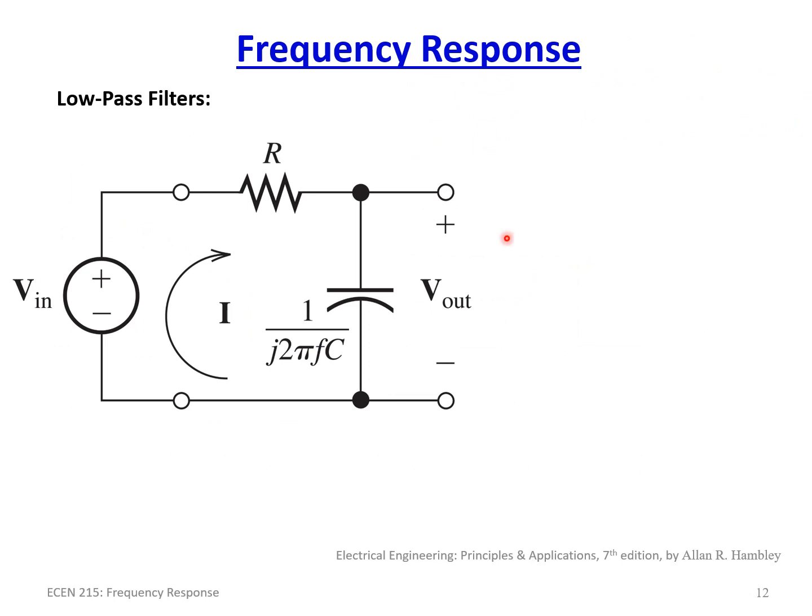So how did we get these transfer functions? So again, we have R and we got our capacitor. So it was simply a resistor and a capacitor. Because we're doing everything in terms of F, when you think about signals, everything is in relation to hertz. So it's 2 pi F. So this is just 1 over j omega c. So that's the impedance. So we've replaced omega with the frequency, 2 pi F. V in over V out. So we go ahead and we would write this.